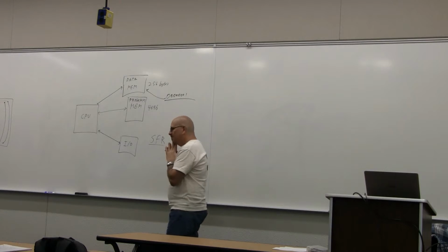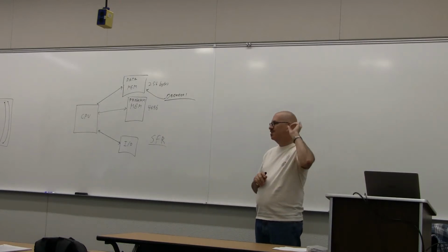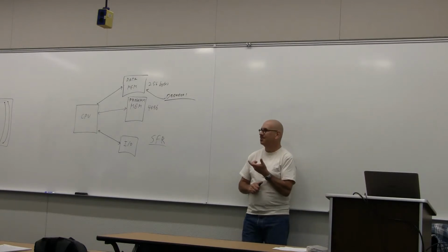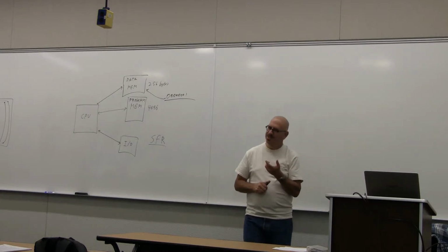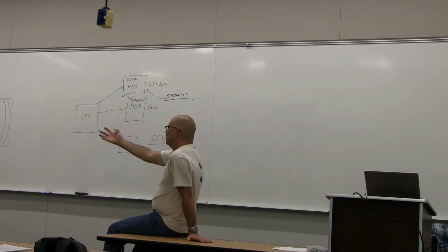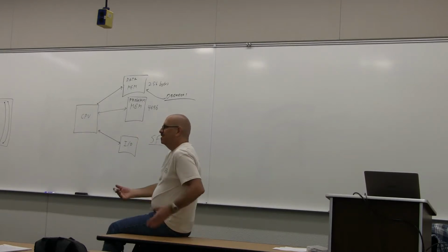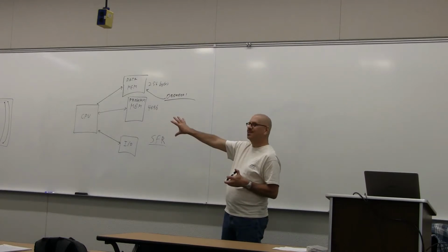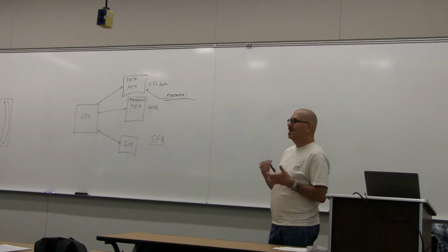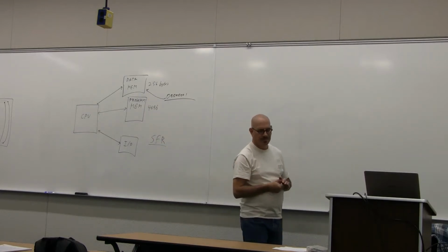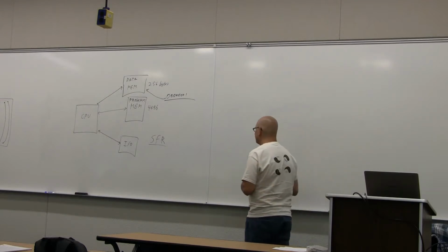All right, well, let's look at our data memory. So 256 bytes. Our basic unit of data is a byte. How many bits in a byte? 8, right? So 8-bit number, small integer, 0 to 255. That's the type of variable we're working with. And yeah, in terms of a PC, that's minuscule. But we're not trying to do things on a PIC that we do with a PC. We're trying to do things like read this sensor, convert it into temperature. If the temperature goes above a certain amount, turn on this alarm. That would be a typical application for a PIC chip. Why? Because it costs $1. And it's a small chip, and you can put it on a circuit board and build it into your lab, right? And have it monitor temperature for you and sound an alarm if the temperature gets too high. So we don't need a whole lot of memory for these kinds of things that we're going to be doing. So 256 variables, if you will, where your variables are just small integers.